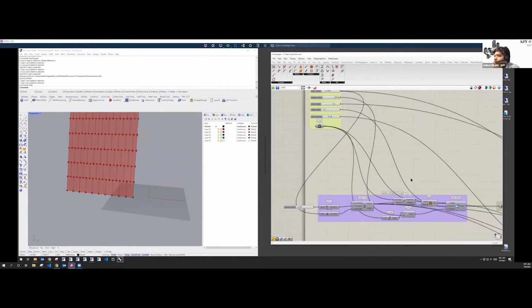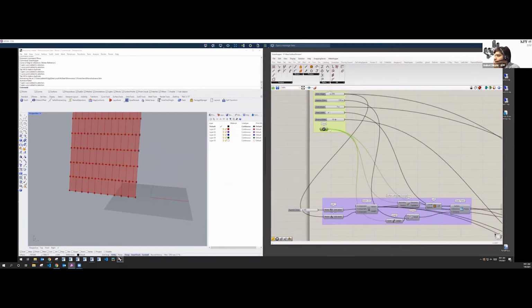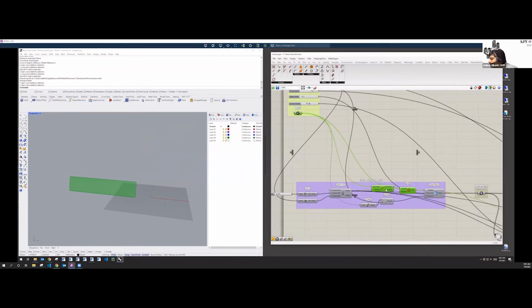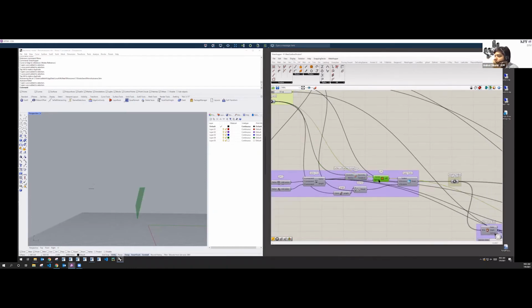So what we're doing is not at all complicated, right? We're taking a curve and we're just extruding that curve so that it's at an angle, so that it's not straight. So there's a certain amount of complexity to the panel, to the curtain wall that we're creating. And once I loft it, there becomes our curtain wall. And then we're using the LunchBox quad panels to create a single floor height of curtain walls.